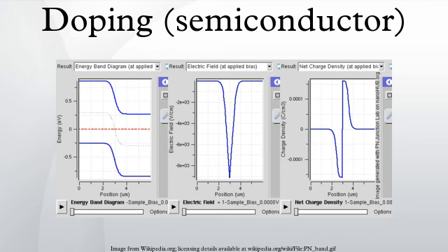Lower dosage of doping is used in other types of thermistors. Compensation. In most cases many types of impurities will be present in the resultant doped semiconductor. If an equal number of donors and acceptors are present in the semiconductor, the extra core electrons provided by the former will be used to satisfy the broken bonds due to the latter, so that doping produces no free carriers